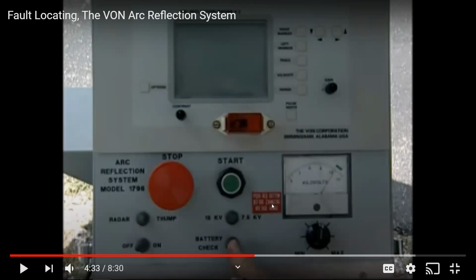What you cannot do, and this is what this little red sign right here says, it's got it in the lid, is start the machine and adjust your voltage. That is a no-no. So if I came up here and started and my cable was a 15 kV cable and it only came up to 4,000 volts, can I turn the knob to adjust it? No, because you're adding even more current, right?